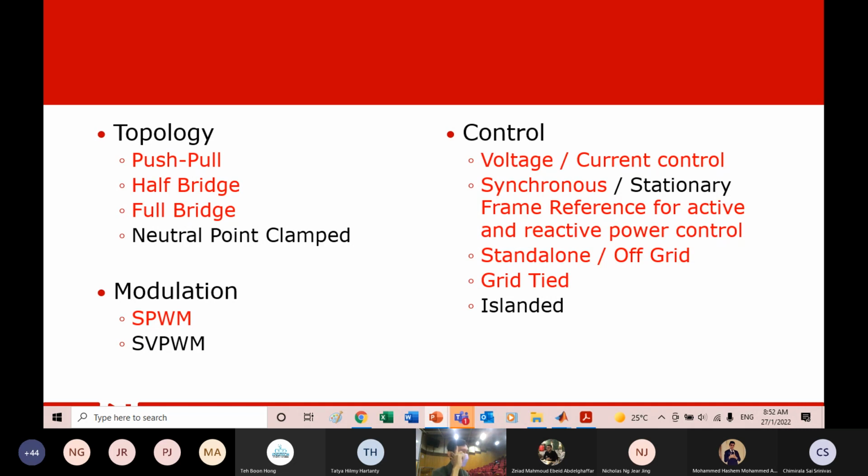Because power cut-off is either by short circuit or for maintenance. The TNB guy will say, oh, we want to change something, we turn off the grid. Then they go out and do the work. But you have a solar system there, and your inverter never knows. At that point, it's called islanded already. Island is just like an island surrounded by water, no more power coming in. You are not connected to anyone, but you have your own power.